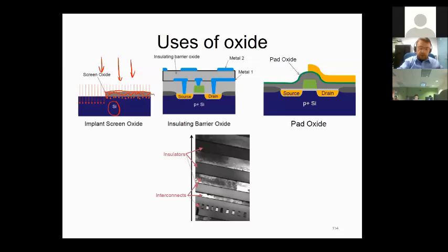We'd like to allow it somewhere. We'd like to block it somewhere. Silicon dioxide is a nice material for masking purposes. As you can see further, we have these used as barrier oxides, so we are enabling non-conduction between the two electrodes. These could go to jumpers here, and these two electrodes, the two signals, will not be shorted to each other thanks to the oxide.